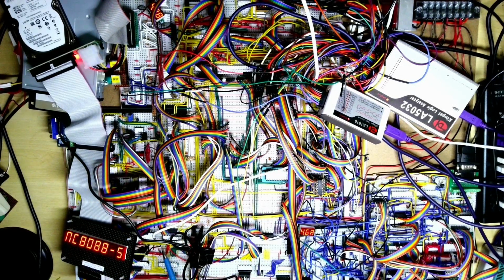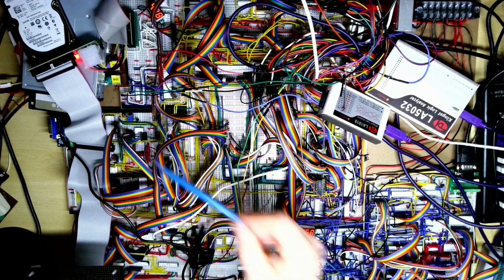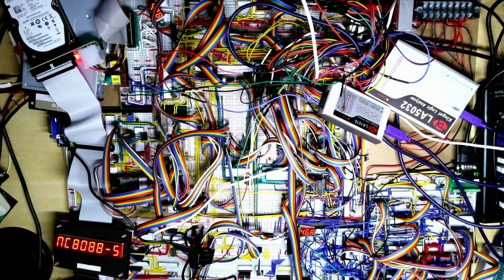Down the bottom here we've got the real-time clock. This has a CMOS backup battery, so the clock actually does run when the computer's turned off. And if we just take the LED display away, the IDE cable, and there's a very simple IDE controller. It's basically a couple of buffers, is really all an IDE controller is. Most of the intelligence is actually in the drive itself up there.